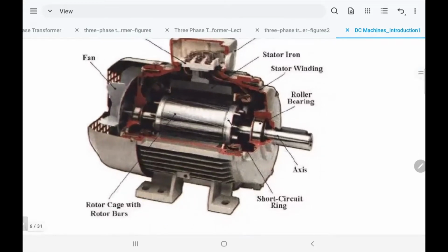It's coupled with the shaft, and there are bearings, mechanical things to minimize the friction, and it also has windings. Usually the wires inside this rotor, put in some slots, we call the armature. So the one in the stator, if it's producing the field, we call it field winding.